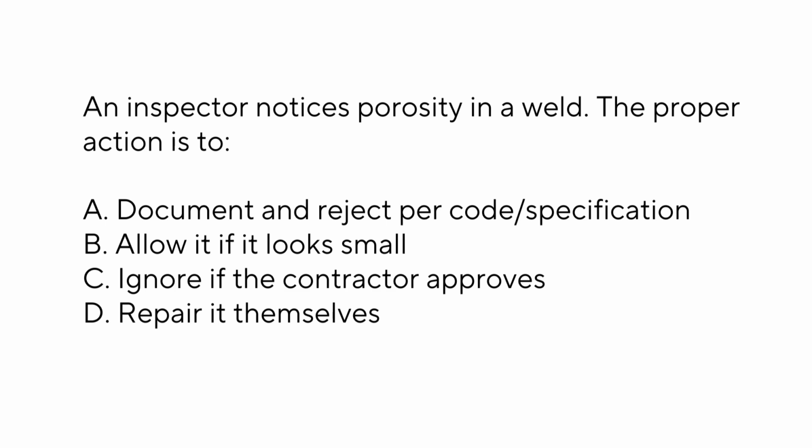An inspector notices porosity in a weld. The proper action is to: A. Document and reject per code/specification, B. Allow it if it looks small, C. Ignore if the contractor approves, D. Repair it themselves. Answer: A. Document and reject per code/specification.